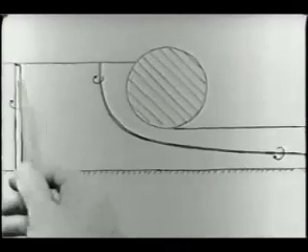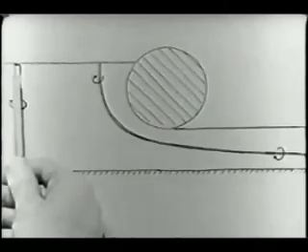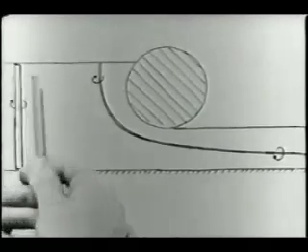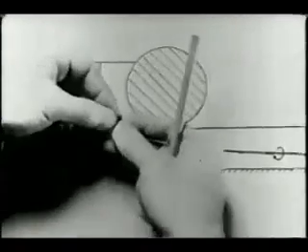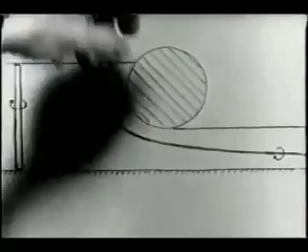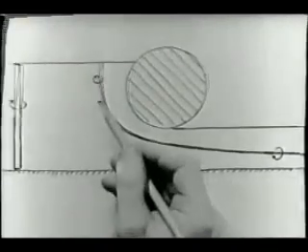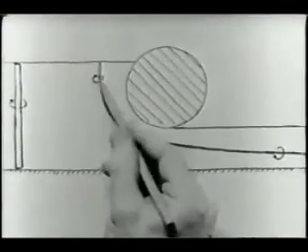Suppose that this thread of fluid coincides with one of the vertical vortex lines. As it moves downstream, it is both bent and stretched. The stretching of the vortex line intensifies the vorticity and makes the vortex core visible. The bending of the line produces a streamwise component of vorticity because the vorticity is locked in the fluid.